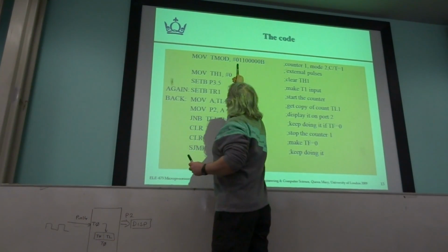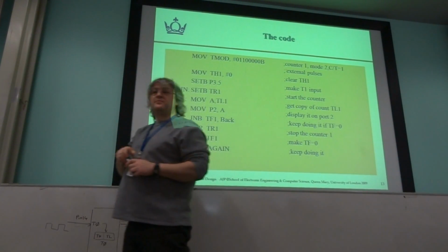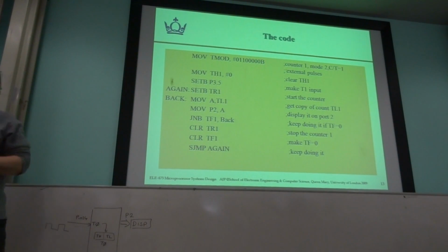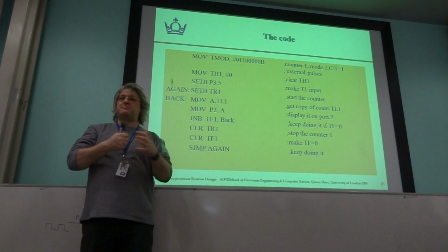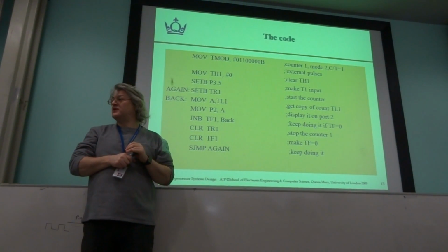This bit here is the gate bit that normally we have low. The gate bit we only make go high when we want to use an external pin to basically suspend the count under our control, to pause things.